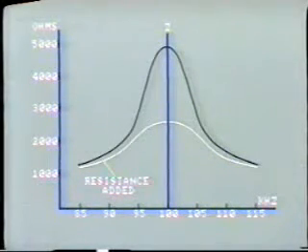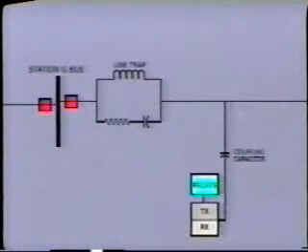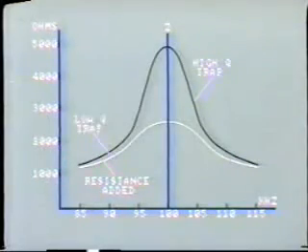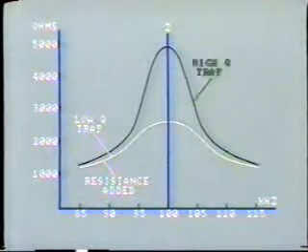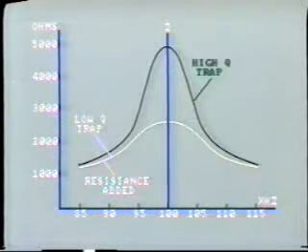This actually has the effect of reducing the impedance at the resonant frequency, but improves the off-frequency operation by providing a resistive characteristic. The resistance is usually connected in the capacitive branch of the line trap, and its value is chosen to match the line characteristic impedance, say 400 ohms. This type of line trap is known as low Q. The high Q wave trap has lower resistance and therefore relatively higher quadrature or reactive component.